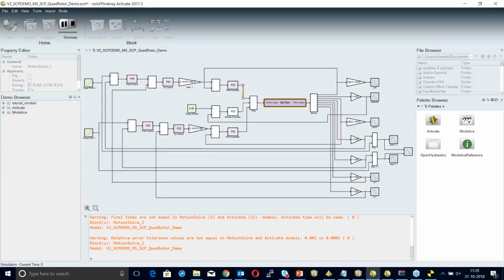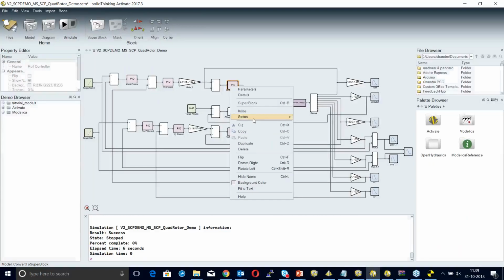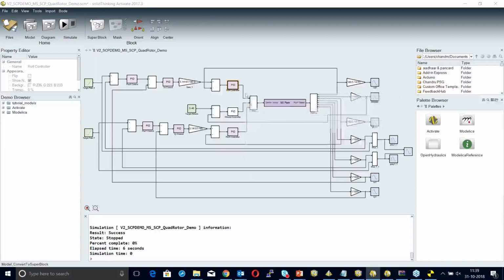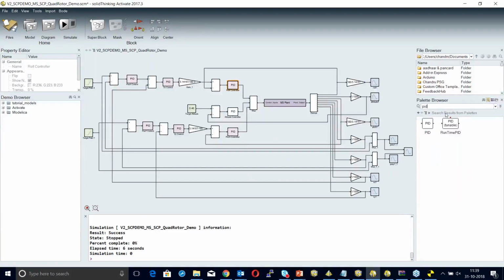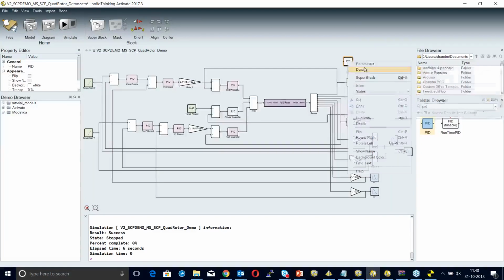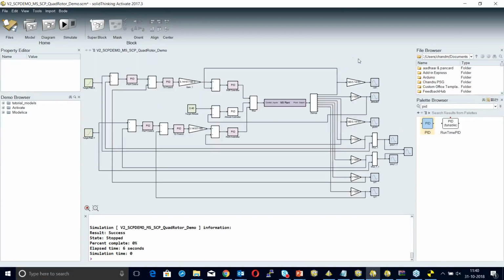And then you should see how to set up these PID values, how you set up your proportional gain, integral gain, and derivative gain. Towards this, if you want to look at this model, you can enter into the model. You have the ready-made PID blocks available here. Here are the PID controllers. You can build your own PID, or you can feed the PID parameters as well, and you can go inside the subsystem block as well.